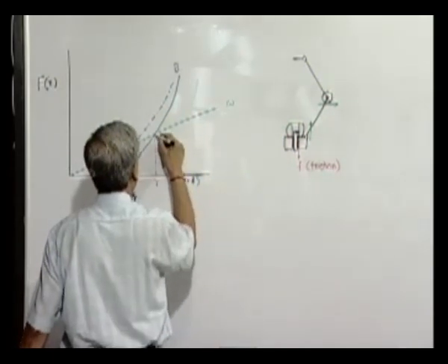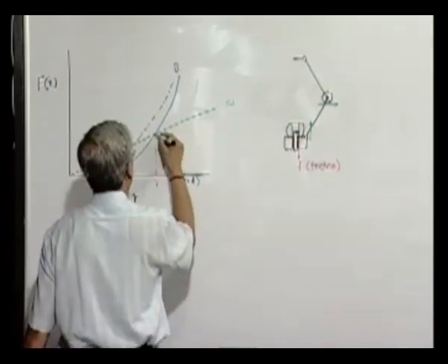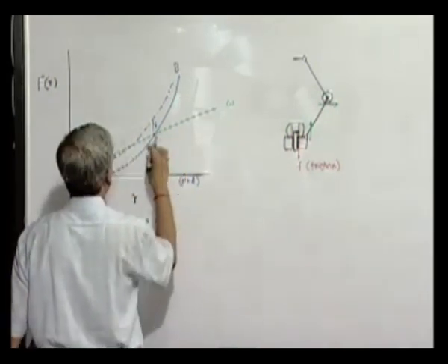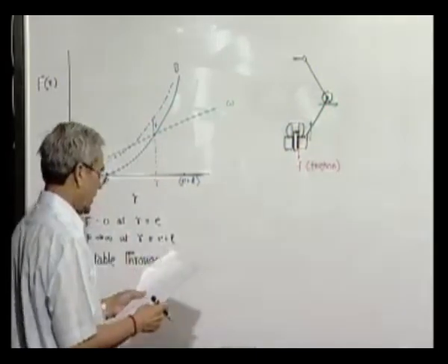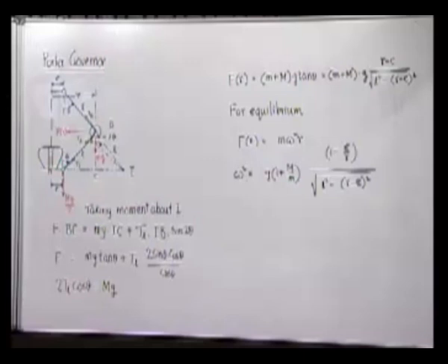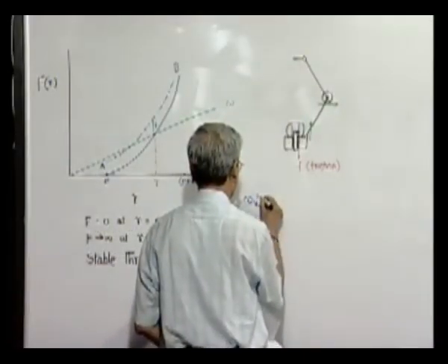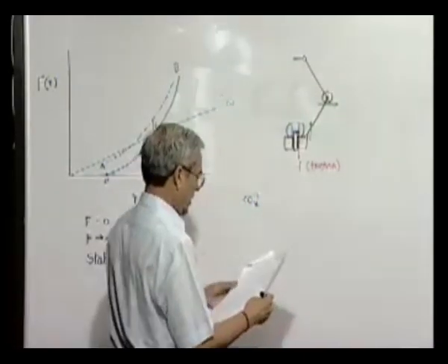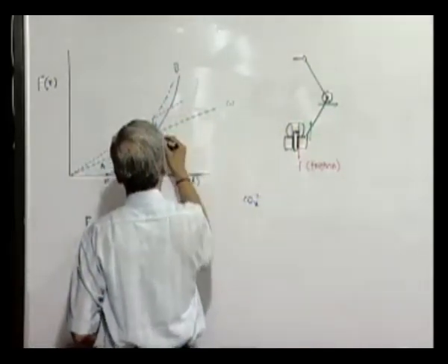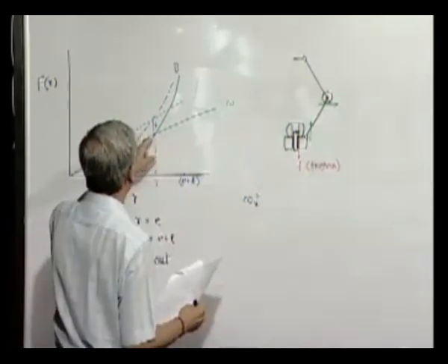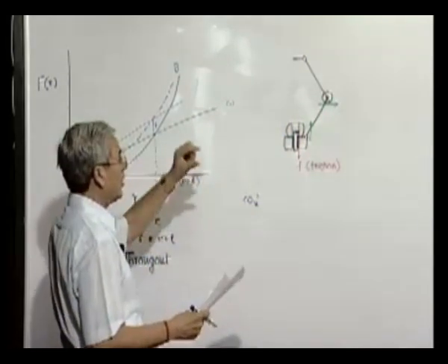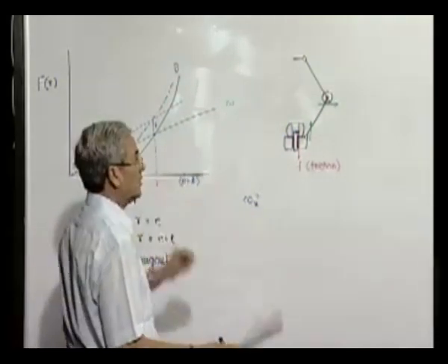So, suppose at that instant it is speeding up. So, the control force curve, the force will be here, which is the total force F, and you have to add a certain amount which is here. So, what you will find there is omega u square, that means when it is going up at the upper limit, at this particular rotation, therefore radius, the governor will be at one location, though the speed may vary, because the friction will take care of that variation.